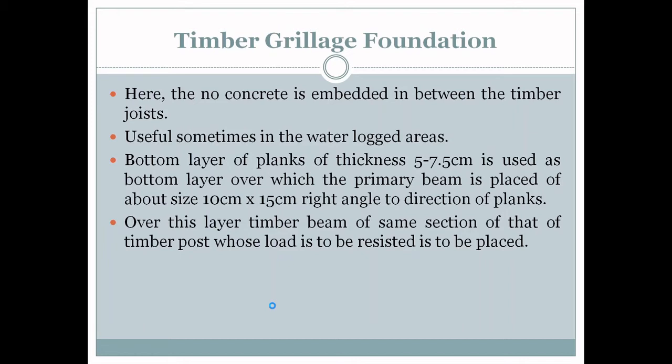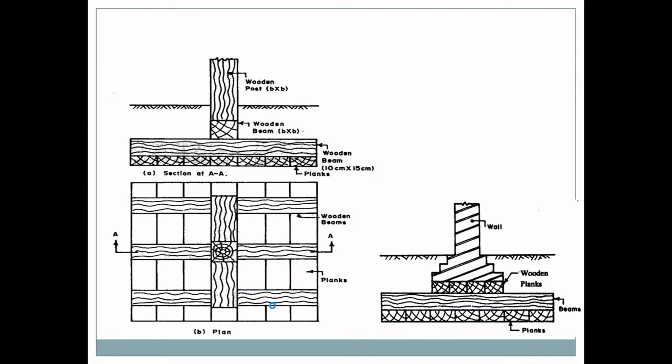The foundation uses timber planks and timber beams in place of steel. No concrete is required in timber grillage foundation. In this figure, you can see the section and the plan of timber grillage foundation.